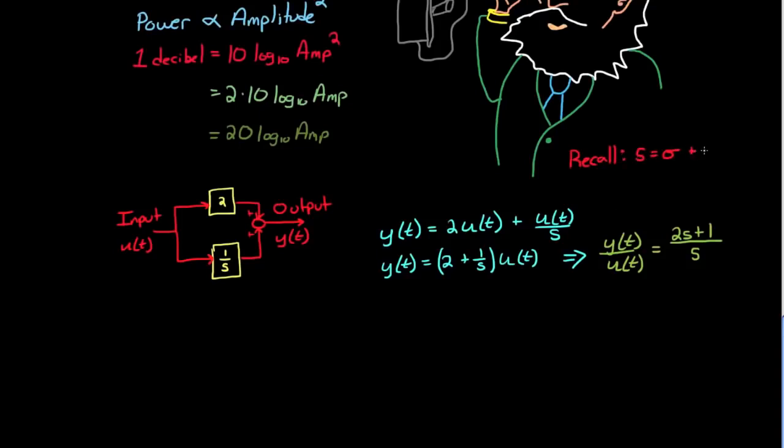However, when we're talking about frequency response of a system, we are talking about the steady state response. That is, once all the transients have died out, or in other words, when the exponential term sigma is 0. So for steady state behavior, s just becomes j omega. Steady state phase and gain can be calculated directly from a transfer function by setting s to j omega.